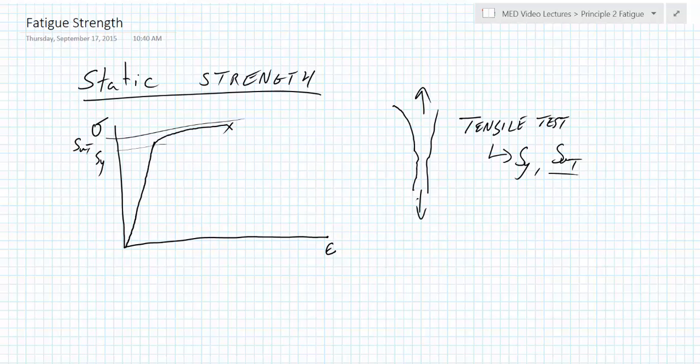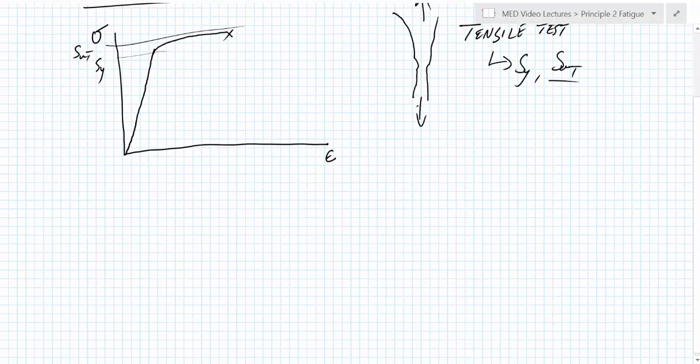In fatigue analysis, it turns out that how we load the thing actually matters. And because there's basically an infinite way of loading things, there's no way that we can come up with an absolute prediction for whether or not something's going to fail. So in practice, when engineers develop a fatigue test stand, what they'll do is they'll take their actual part and put it through the fatigue test rather than trusting these generic properties. But let's go ahead and figure out how we come up with these generic properties.